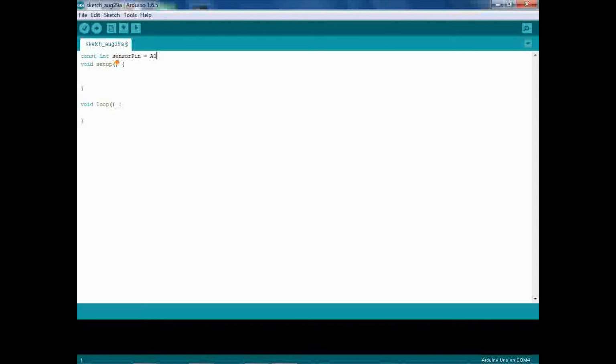If you remember in our schematic diagram, we have our sensor pin plugged in at A0. Okay. All right. So this sensor pin, make this float. This sensor pin will require a baseline number for comparison, and so that's what our second constant will be. The function we'll use is baseline temp equal to 20.0 and a semicolon.